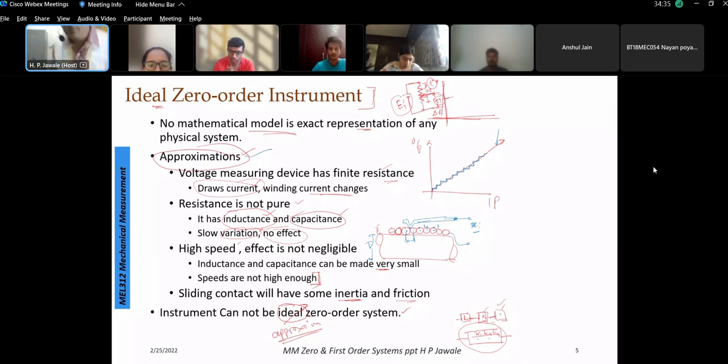And also you'll find that to overcome this, we are going to have the continuous resistance in the form of a film. See, if I am going to make a carbon film of given length, a very thin layer, and if I am going to have this as one terminal, this as the second terminal, and if the slider is moving now instantly from one point to the other, we will find it is giving more clear understanding.